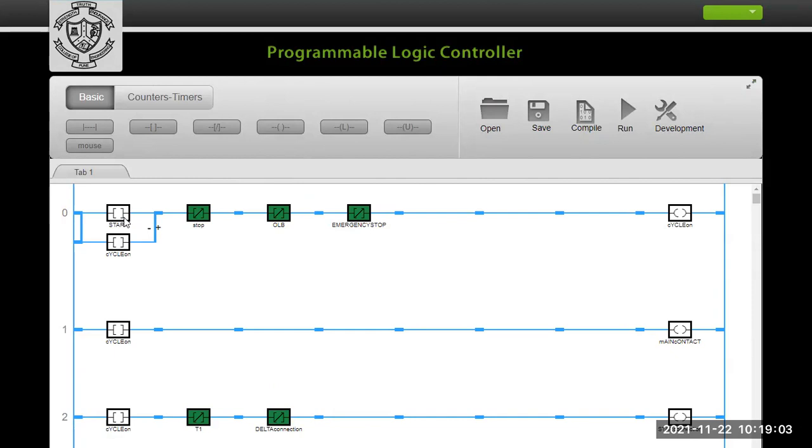First, whenever you press the start push button, your system will start. The rung will go on, and your first cycle is on, meaning the start delta motor cycle is started first. Look, here is the latching, so it holds on. Once you press your start button and then release it, due to latching it will keep going.